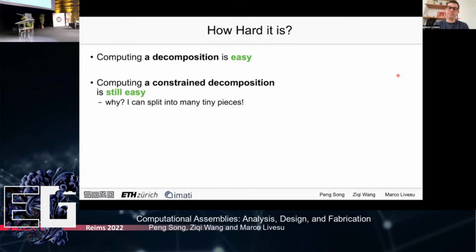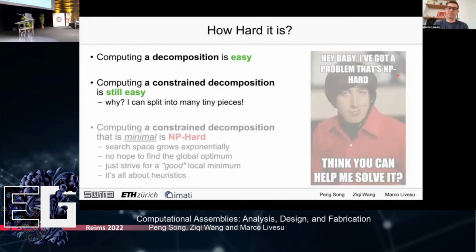The reason it's easy is because you can still play with the size and the number of your objects. So you have 2 degrees of freedom, which are unbounded. And if you play with them, for example, creating just tiny pieces, it's very easy. For example, if you want to decompose a very complex object into a bunch of height fields, if you create tiny height fields just by cutting every convex vertex of your mesh with a plane, it's not complex. It's completely useless, because at the end of the day, you will get millions of elements. But for the sake of decomposition, that's not a complex problem.